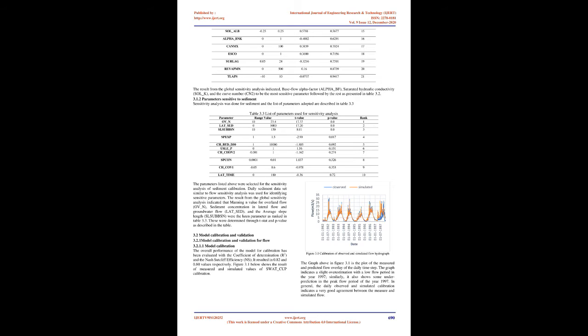The coefficient of determination, R2, is an indicator of the strength of the relationship between the observed and simulated values. It is computed by equation 2.1, where the first variable is the observed, measured, stream flow on day i, m3/s, the second is the simulated stream flow on day i, m3/s, then the mean observed, measured, stream flow, m3/s, and the mean simulated stream flow, m3/s.